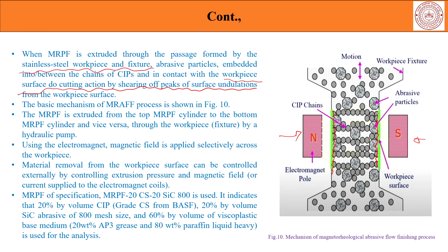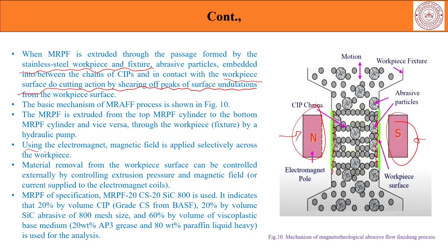As the abrasives are pushed through this densification process, particularly in the magnetic field zone, you see suddenly there is an organization effect of the CIPs, which leads to a zone of apparently higher hardness or higher viscosity, and this gives you a sort of pushing outwards effect, and the cutting forces of the abrasive grains which pass in this manner to shear off those small striations coming off the surface are suddenly increased because of such outward pressure, which comes because of the change in the viscosity because of lining up of the magnetic material.